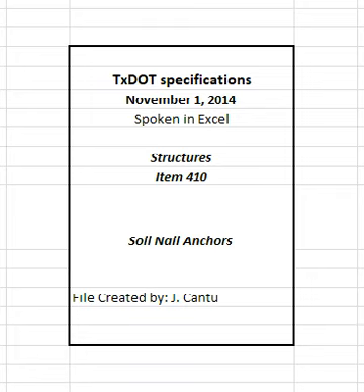Furnish a hydraulic jack and reaction frame for stressing the test anchors. Furnish a pressure gauge for the jack that is graduated in 75 psi increments or less. Furnish a minimum of 2 dial gauges capable of measuring to 0.001 inches. Calibrate the hydraulic jack and ram used together as a system, and furnish certified copies of load calibration curves for all jacks and ram systems to be used in the work. Calibrate the jack and ram as a unit no more than 6 months before starting work. Recalibrate stressing systems when directed or at least every 6 months. Furnish a grout mixer and pump of sufficient capacity to place grout properly in the required quantities.